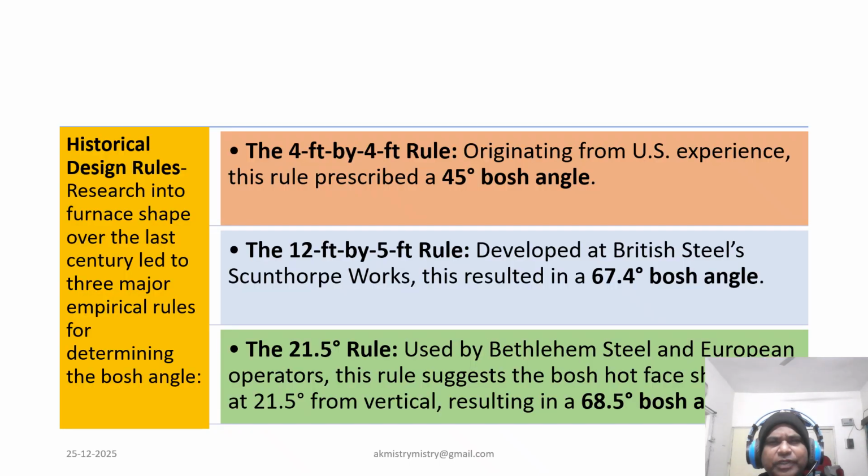In modern blast furnace design, we have moved towards much steeper profiles. The typical modern Bosh angle now ranges between 70 degrees and 85 degrees. This trend is primarily driven by productivity. A steeper angle maximizes the furnace's internal working volume, allowing for more material processing.